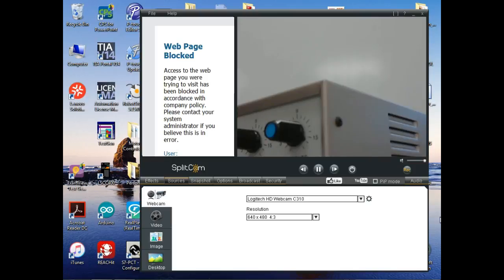So you get out there and you fire up your line at the same time and you start 20 motors at the same time, you're talking about a massive inrush current. So a lot of times what they'll do is they'll time delay, they'll stagger start the motors. They'll start one and after time they'll do what? They'll start another and start another. You'll see that all the time. You prevent that massive inrush when we're trying to start a bunch of motors at the same time.